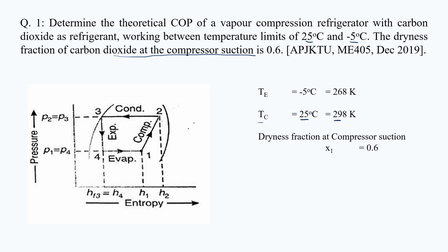As we had discussed earlier, since the location of point 2 inside the curve is not known, we have to find out the dryness fraction of state 2. Also, since the data is not given, we cannot assume point 2 is actually lying on the saturated vapor line. Also, it is better to do this problem using analytical methods, that is using charts, rather than the graphical method.